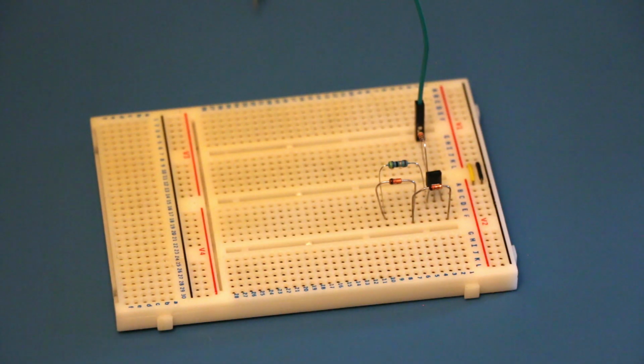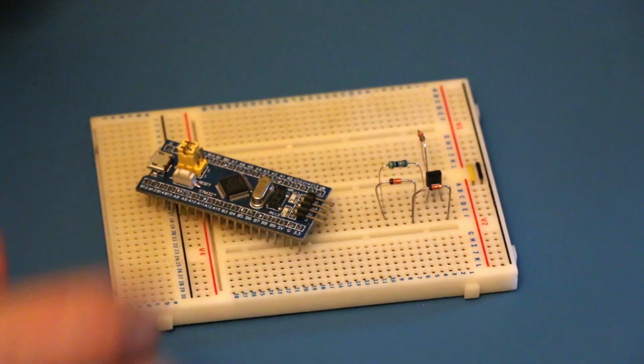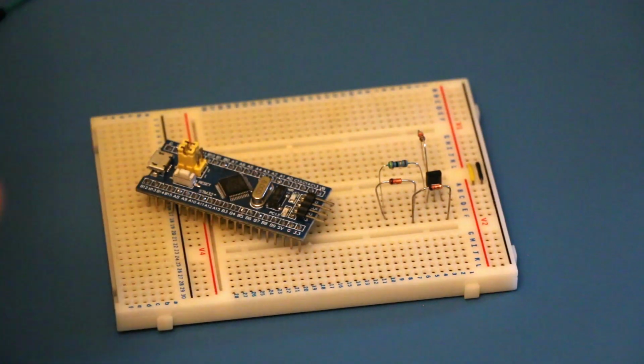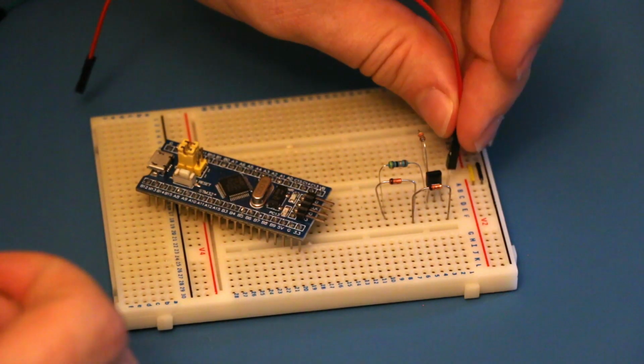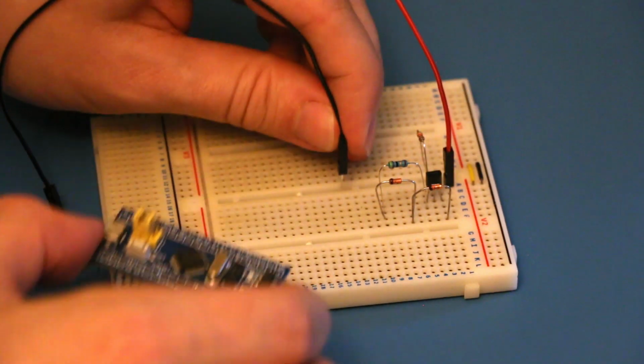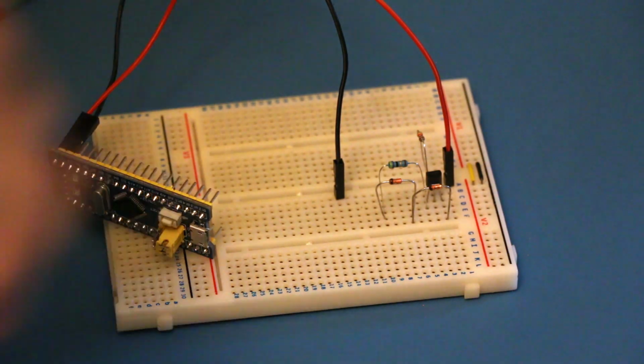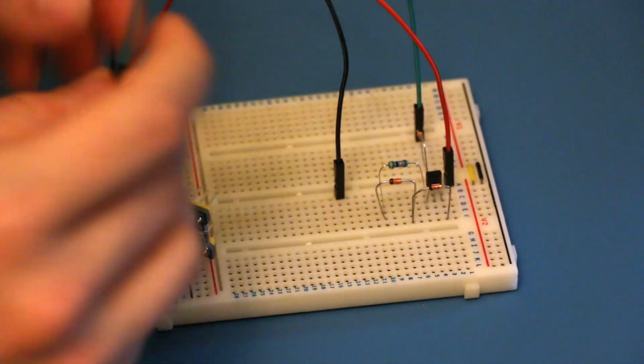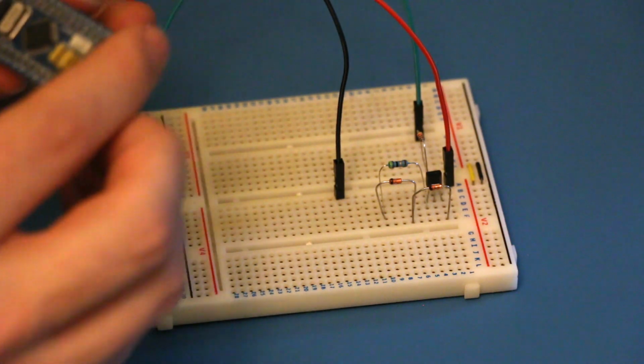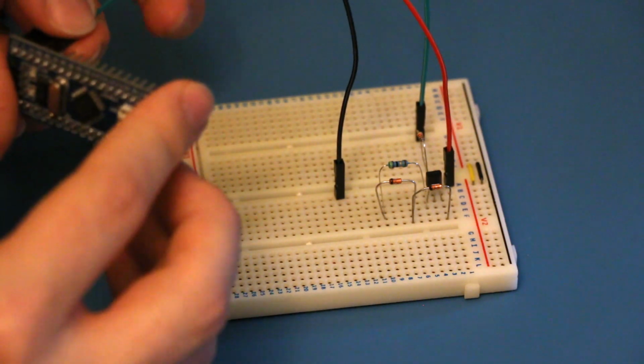I'm going to wire up the dev board to the circuit we've laid out on the breadboard here. The dev board provides us with 3.3 volts, which means we can just use that supply to run the LED chain. And then, because we only intend to bit bang the signal to begin with, we can use any standard GPIO pin for the base of that transistor. So I'm going to go for B9, as that's nice and close to the other signals.